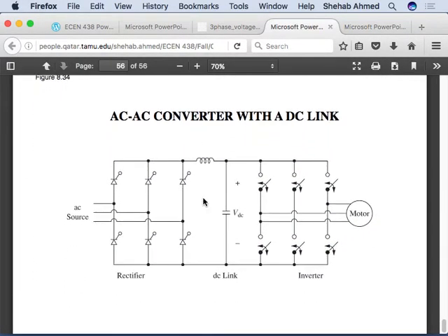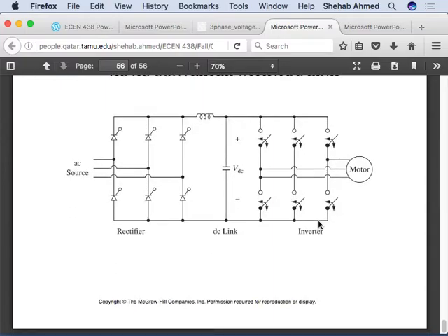And this is a block diagram of a more detailed DC to AC inverter. So this is the three-phase SCR based rectifier. Here I can control my DC output voltage using the thyristor bridge, a thyristor rectifier, and then I can take this DC converted to AC into the motor. So this is the most common application. So this really ends the chapter.